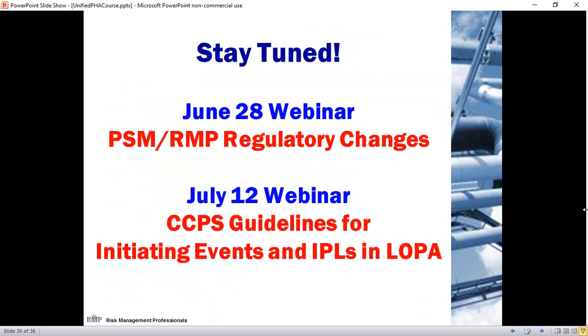When you're putting causes together from a process dynamics perspective, if you close a manual valve, or if a flow control valve closes, or if a transmitter fails to cause the control valve to close, in all cases you may have a no-flow case for that line segment. So the consequences are going to be the same, but the safeguards, the protection features, and also the probabilities may be quite different.